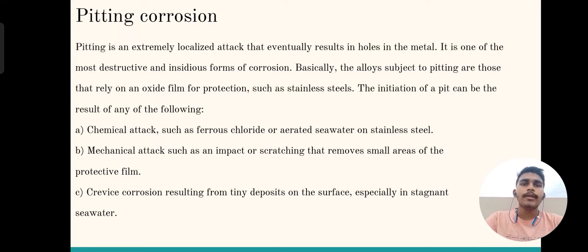Pitting corrosion. Pitting is an extremely localized attack that eventually results in holes in the metal. It is one of the most destructive and insidious forms of corrosion. Basically, the alloys subject to pitting are those that rely on an oxide film for protection, such as stainless steels. The initiation of a pit can be a result of any of the following: